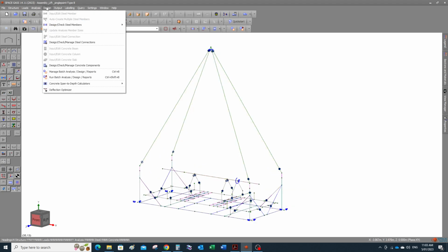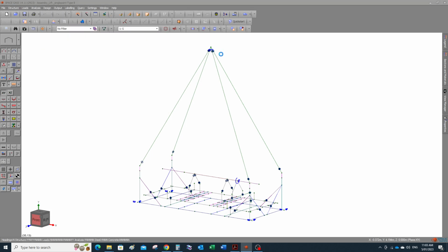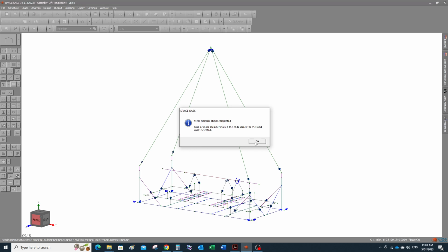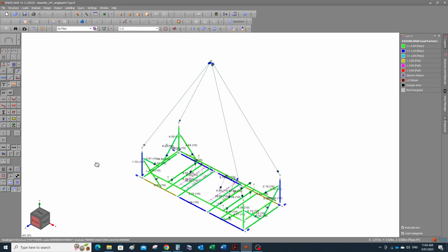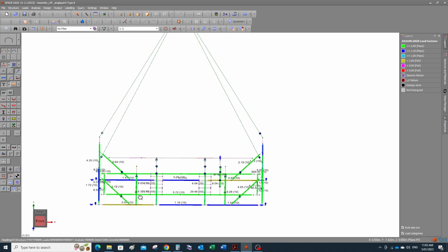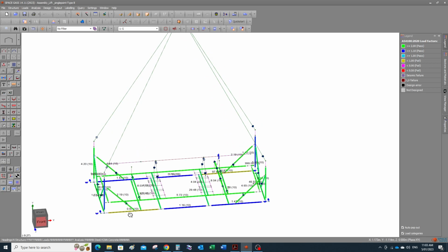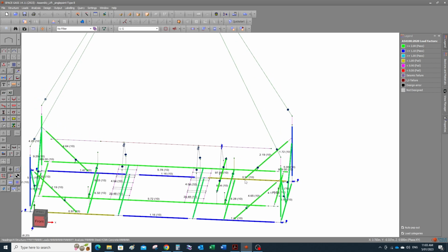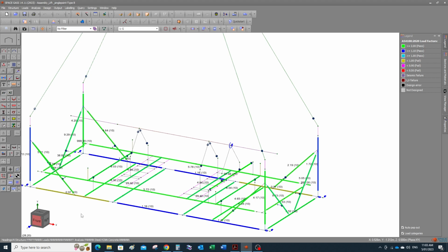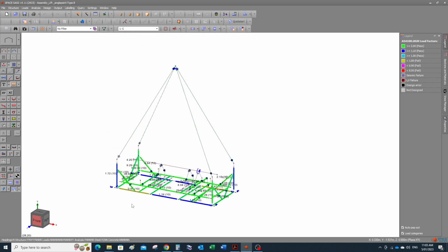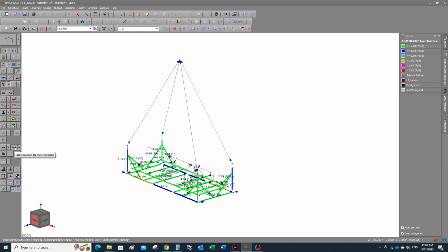And the effect on the design, on this particular design actually, is quite significant. We can see some of the members are slightly failing, so these members that used to pass are now about 3% overstressed, which is not good, but still may be accepted.